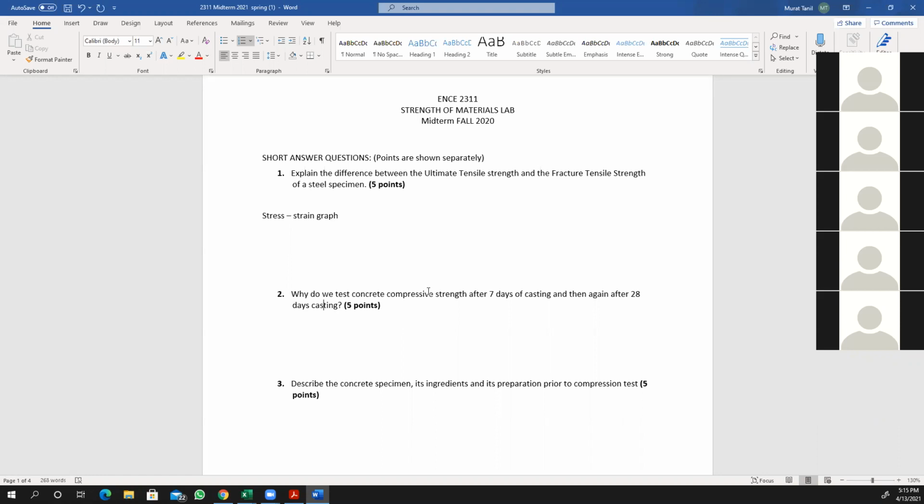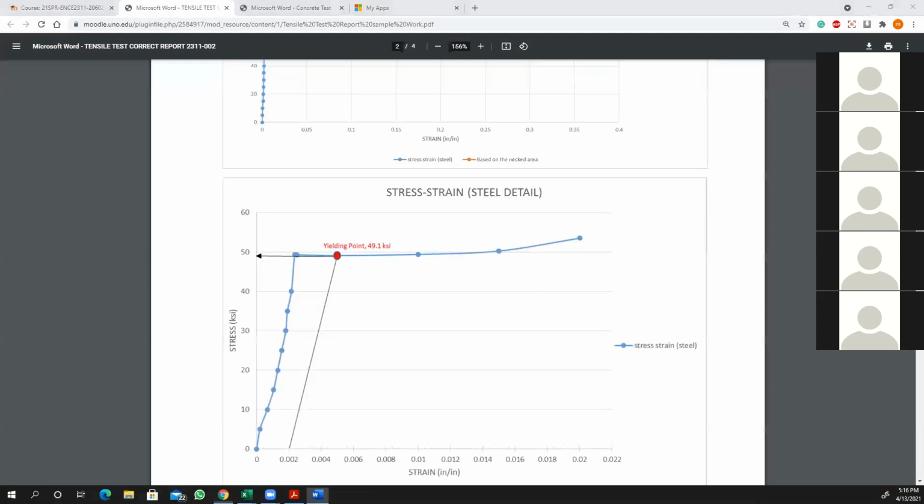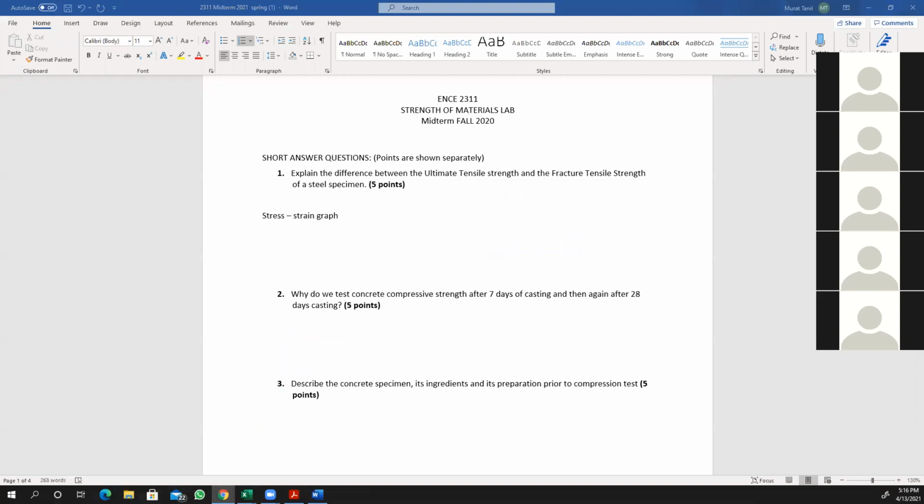Does that make sense? So you get your result in 3 days, and that 3-day result is also giving you the 28-day forecast. So you know, based on the statistical calculations, that plus or minus, let's say 5%, you will get a minimum 4,000 psi. Once you get that okay from the concrete lab, then you can proceed. You can remove your concrete forms, and you can continue your construction process. Is that clear for everybody? Okay, yes. Go ahead, Tere.